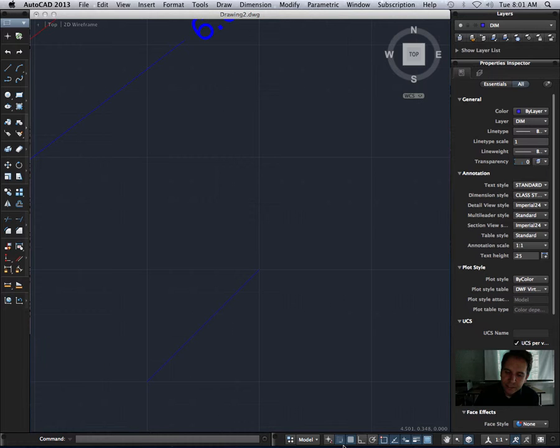quickly draw items that are pretty precise as long as they will actually need to be placed right where these grids are. If I turn this off and do the same thing, now you notice my cursor isn't jumping around, and I can now place a line anywhere. So zigzag right along here. Then our next tab over here is to turn our grid off and on.